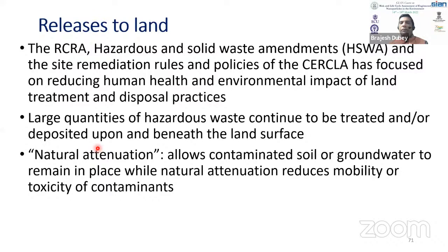From the landfills, things get into the land. There have been cases where we are worried about nanoparticle-containing waste getting into the landfill. Now we have the liner system at the bottom. If the nanoparticle stays as a nanoparticle, with the particle size being so small, will it penetrate through the liner? If it can penetrate through our human skin, it can penetrate through the liner too, and it can go into the subsurface. Those are the kinds of issues we need to look at. In terms of other contaminants, we do see things coming in from hazardous waste.